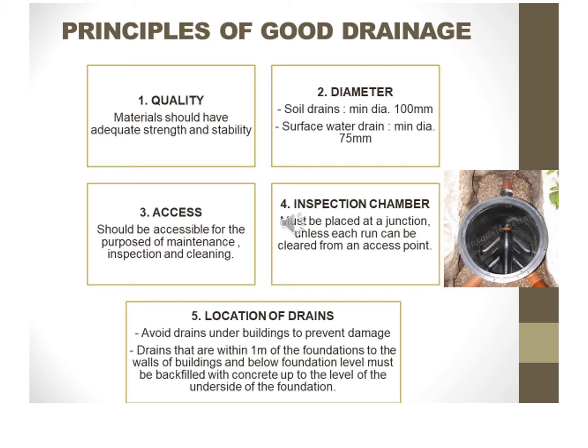The location of drains must avoid going under buildings to prevent damage, and drains that are within 1 meter of the foundations to the walls of buildings and below foundation level must be backfilled with concrete up to the level of the underside of the foundation.